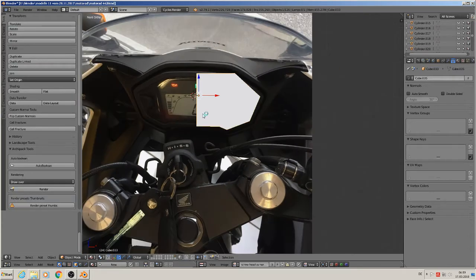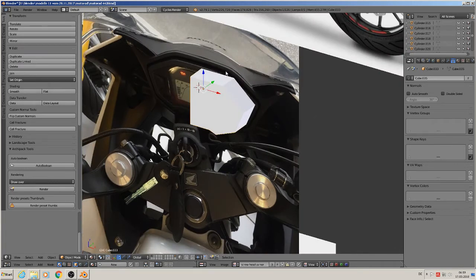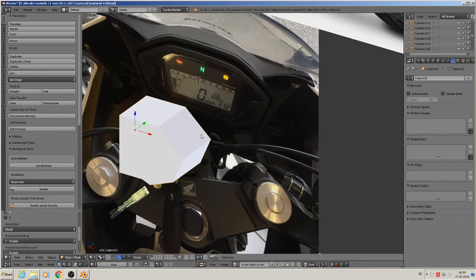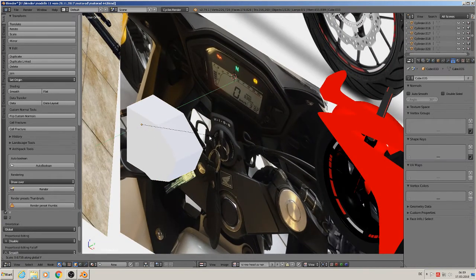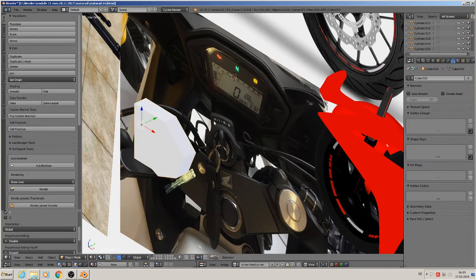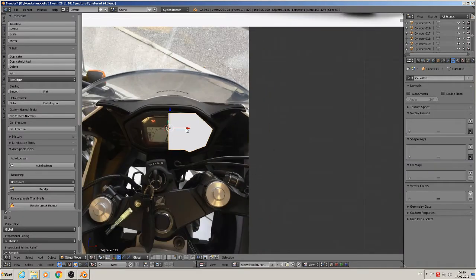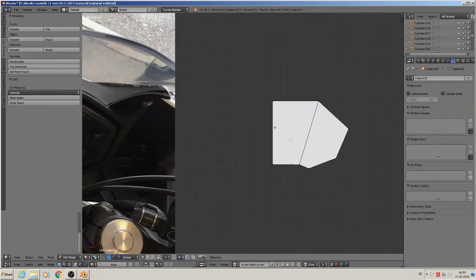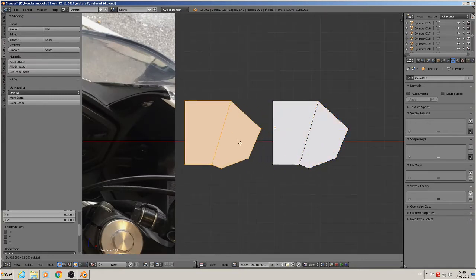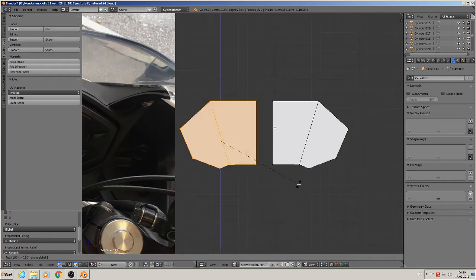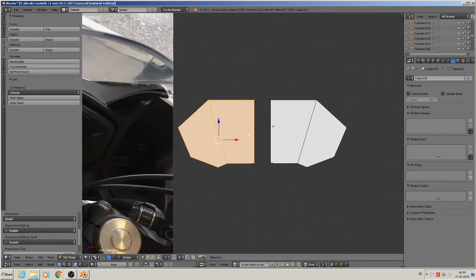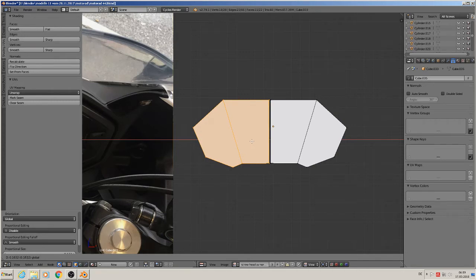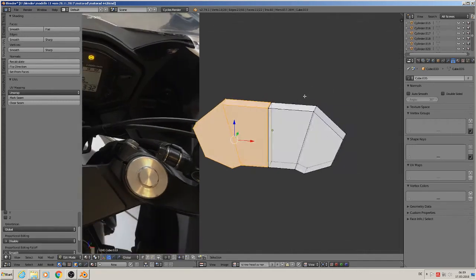Good. That is the base mesh, as many times before. We make them smaller, so scale Y. Good. Then we go here, edit mode, select all with A, Shift D, rotate set 180. Then we merge them together here.